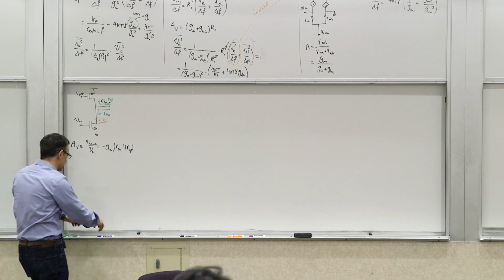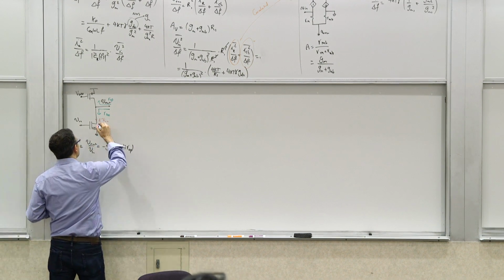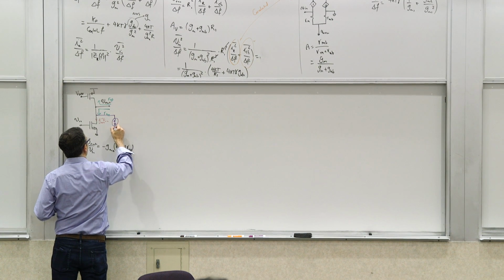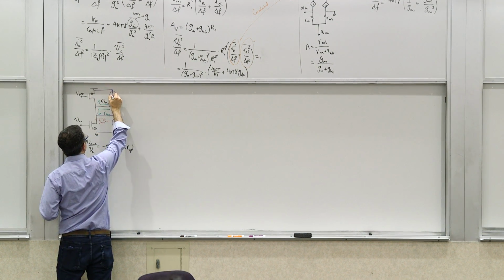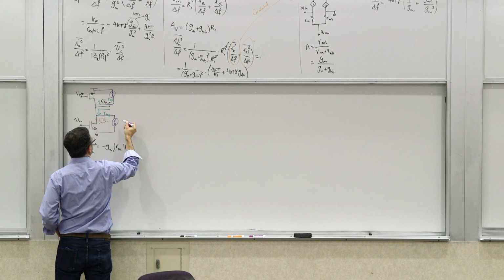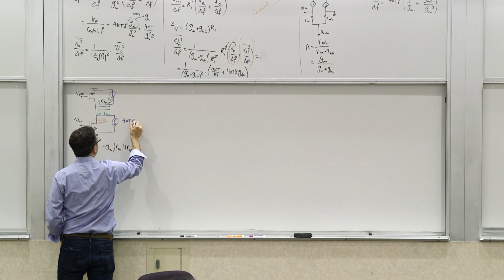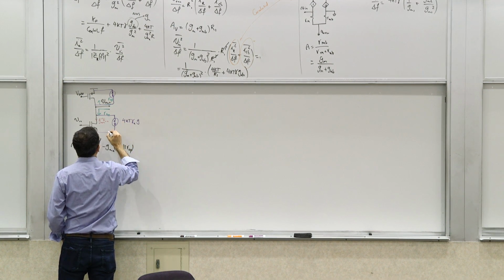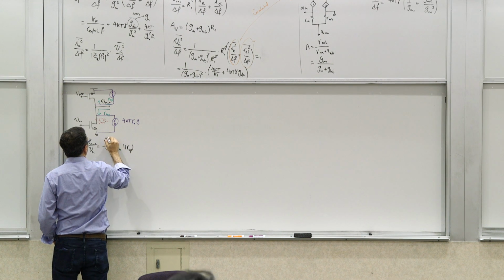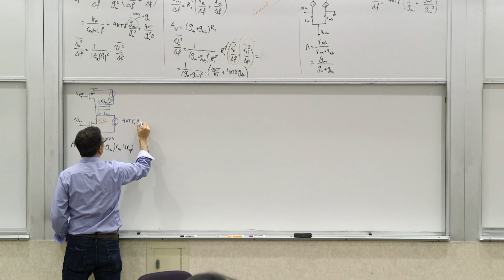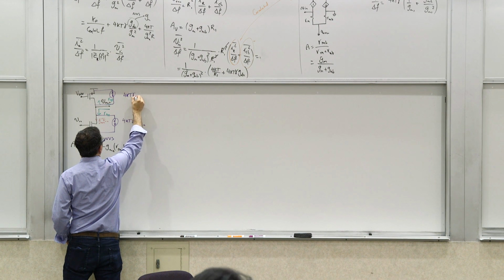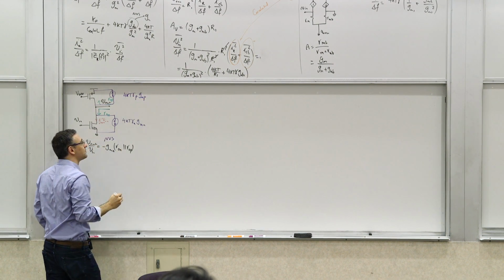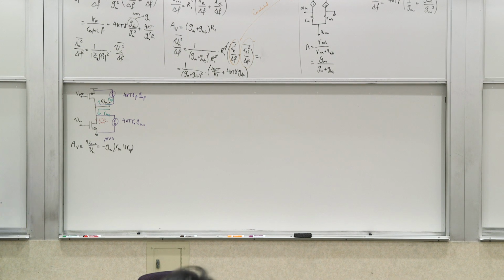Now how about the noise sources? Let's do them in steps. First, let's look at the channel noise of the two transistors. And what is this one? This is 4 KT gamma N GMN, assuming they're non-velocity saturated. And then this is 4 KT gamma P GMP, right? If those are the noise sources, they are injected into something to produce the output voltage.